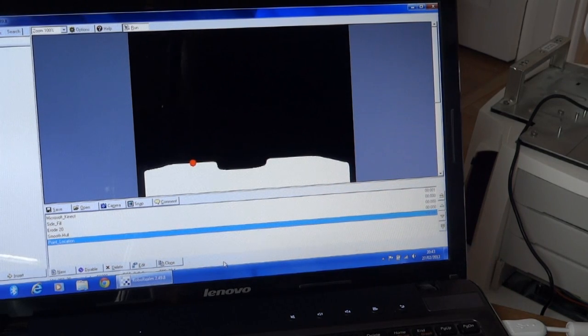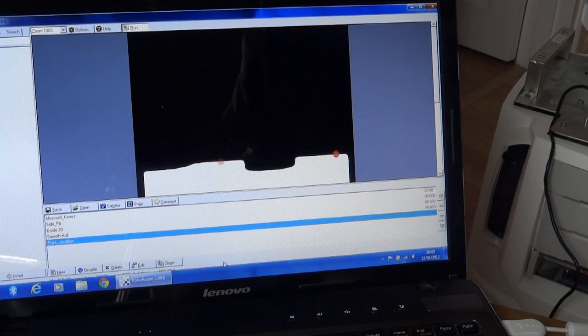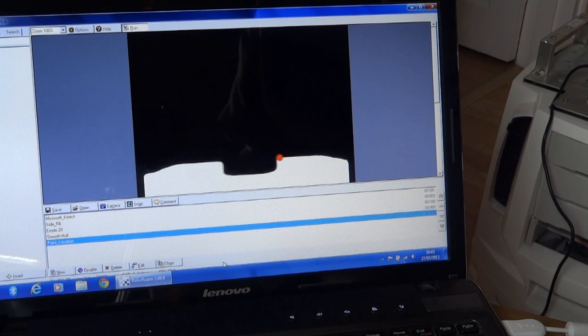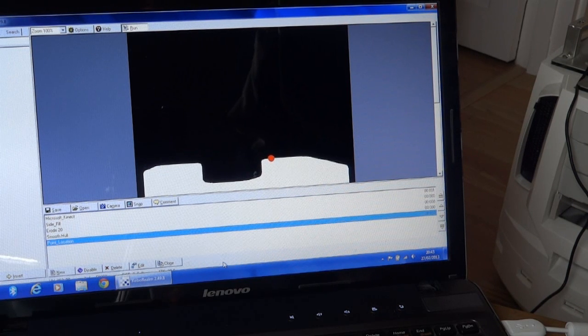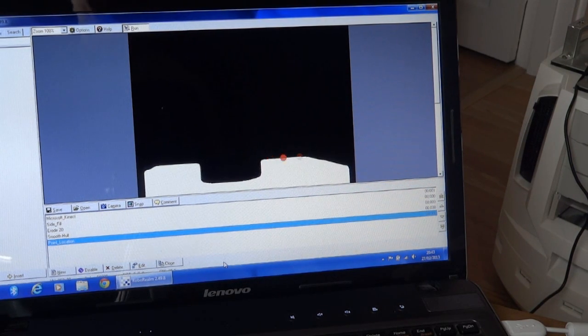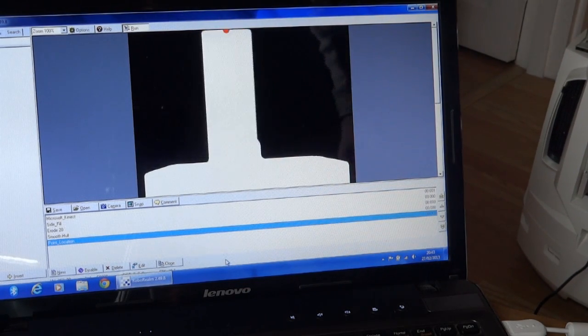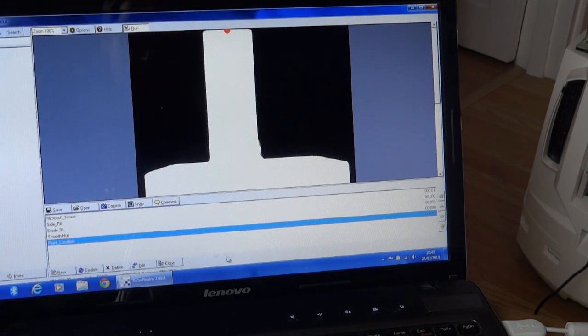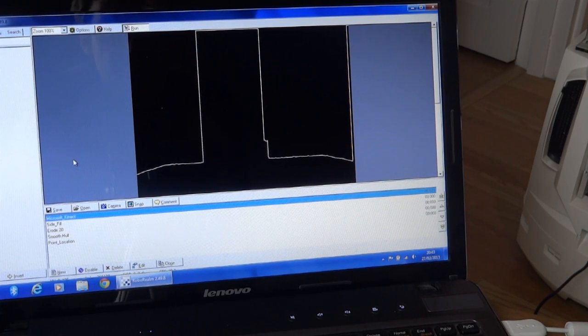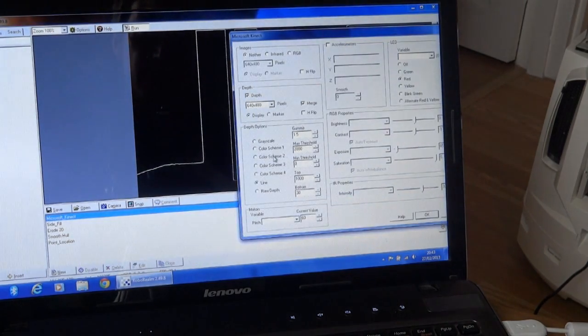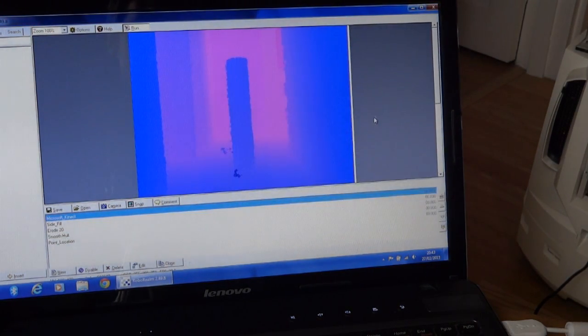So that would tell the robot to travel to the left slightly, and you can immediately see the problem there, that with an obstacle in the way it doesn't know which way to go. The other issue is once the obstacle gets too close, then this happens. And if we look back to the laser line, the line shoots straight to the top, and that's because basically the object is out of range, it's too close. So in fact that's not the correct image.